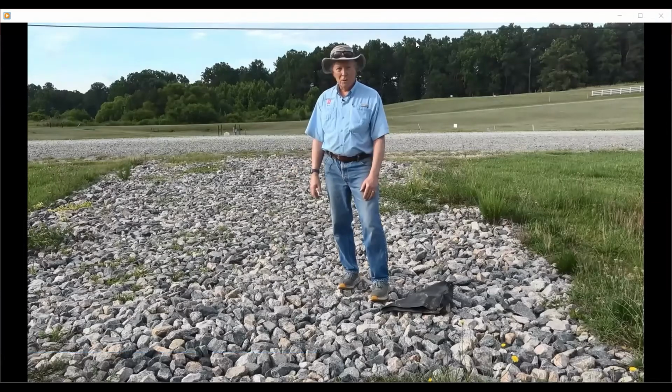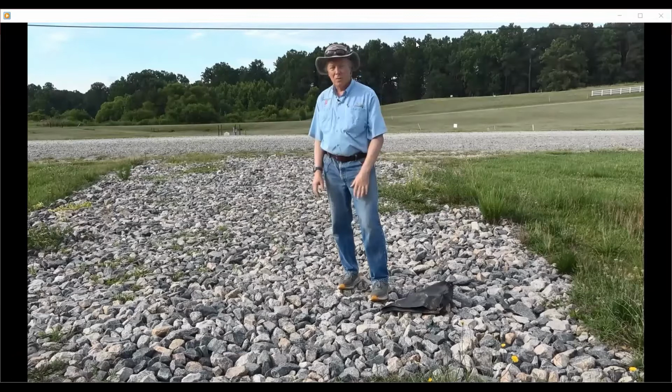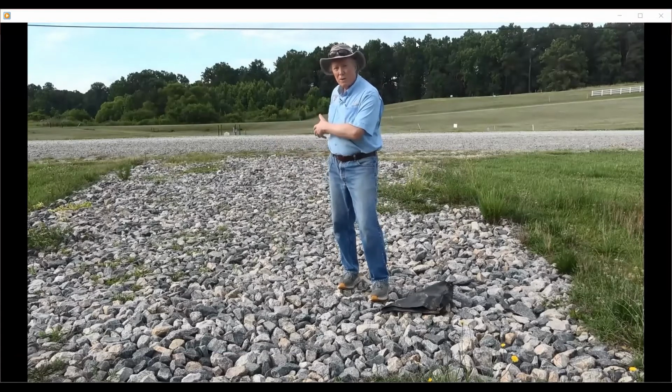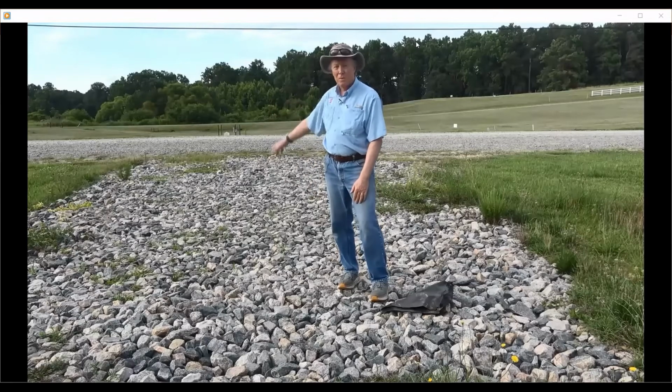There are some commercial products, such as those that are made of corrugated metal. They also vibrate the tires as the vehicles are moving out onto the road. There are some that are based on cross ties. Those are used in forestry frequently. And then kind of scaling it up a little bit, we can actually park somebody with a pressure washer out here, and they can wash those tires individually. Those are cases where we really want to make sure there's not any tracking out onto the road.